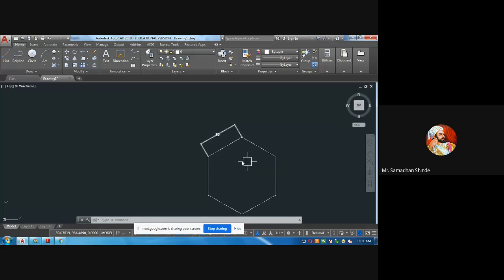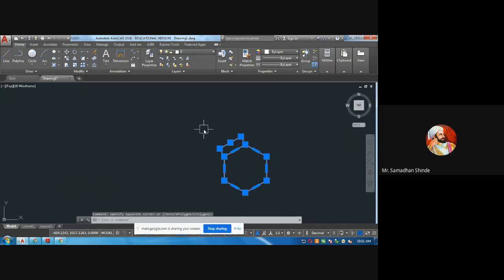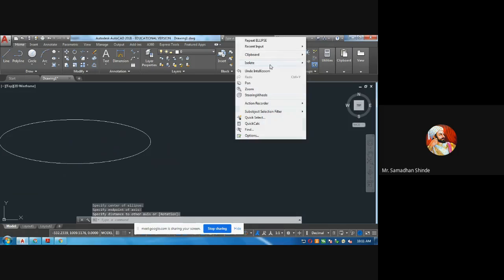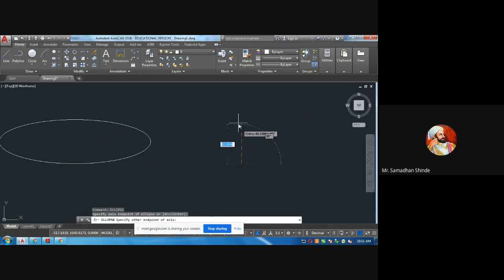So we have seen this also, draw toolbar. Okay, slowly I will go. Then ellipse, we have seen ellipse, how we can draw the ellipse. Ellipse, center, one circle, another circle. So rarely we require to draw ellipse, very rarely, not always. So what inputs are required to draw ellipse? One is major axis and minor axis. If you know the major and minor axis, we can draw ellipse.